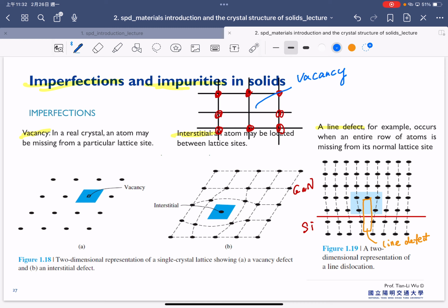So if we have a vacancy in our semiconductor material, the problem is that it can have some additional carrier come from outside, who might just come here and sit in this place and become negatively charged. For example, this is the case of the electron here. And that creates the issues that we usually call trapping issues.